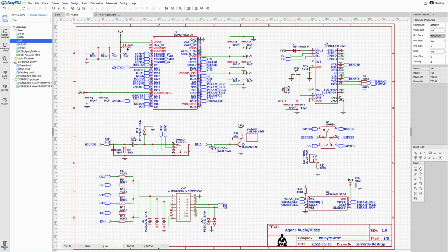The inductor does the same thing, but for current. It resists changes in current. So you could consider adding this coil here as another form of bypass, in the sense that it tries to keep the power level stable into these 2 inputs of the ESP32. The VDDA 3P3 are 2 inputs, and you want them to have a very, very stable power signal.